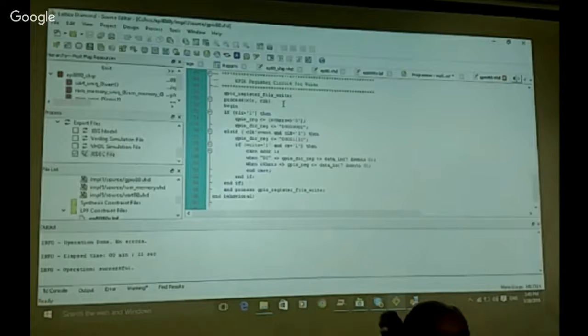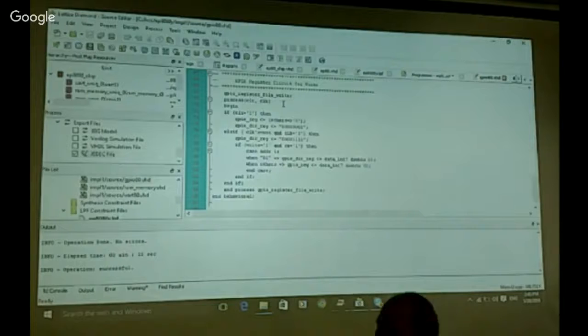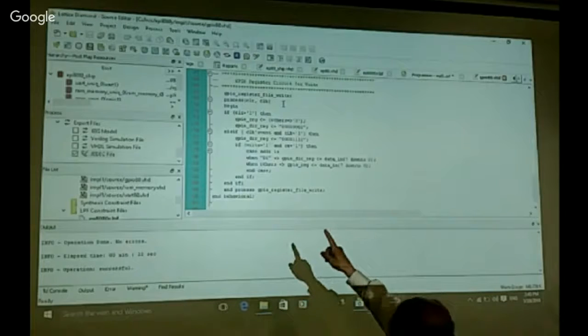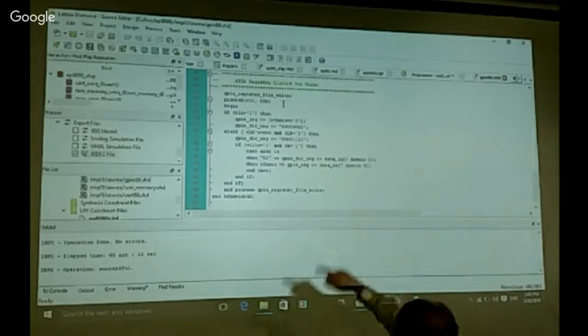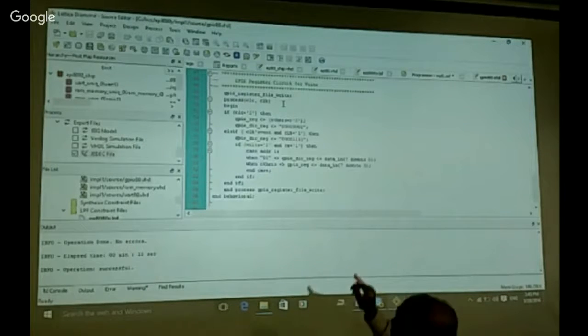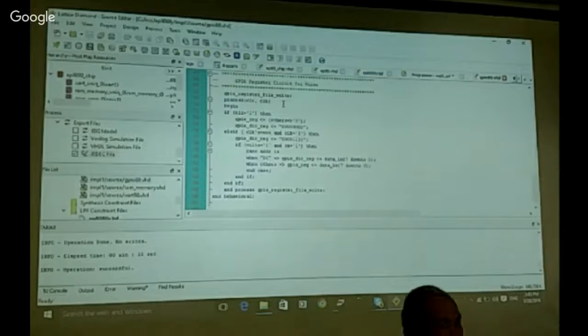But once the clear signal is released, it sets up the direction, the least significant 4 bits as a 1, that specify these 4 LEDs connect to output ports. By default, this LED logic is inverted, so by default it's outputting 0, but the LED lights up when you give it.